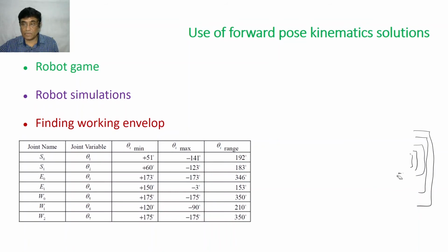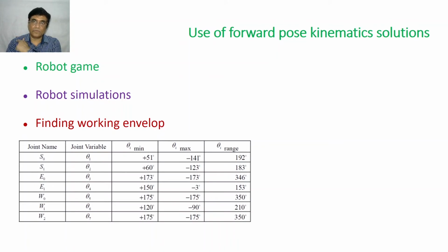This is very important. Modeling first means your forward kinematics or forward pose estimation model. One more thing you can do, in teach pendant mode by pick and place, you bring the robot somewhere and all the joint angles are memorized. Next time you keep some object where the robot gripper, in an open gripper configuration, will reach it, and you just add close gripper.